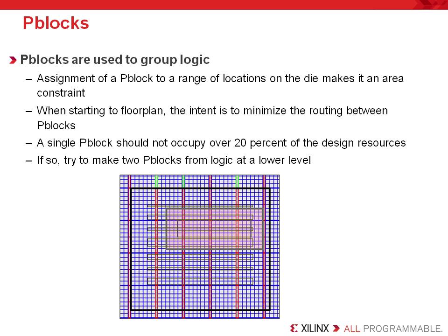Some designs can contain Pblocks that are larger than 20% of the device area, but these cases are rare. If so, try to make 2 Pblocks from logic at a lower level.